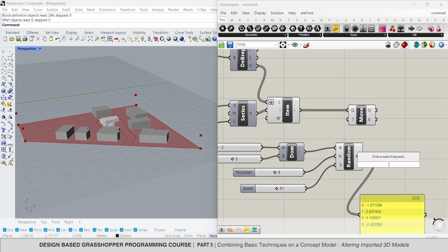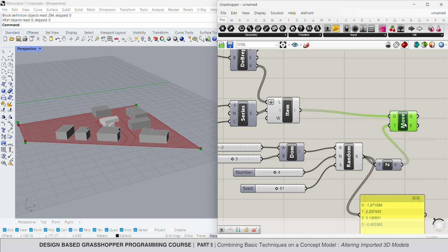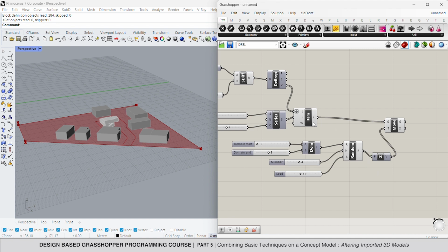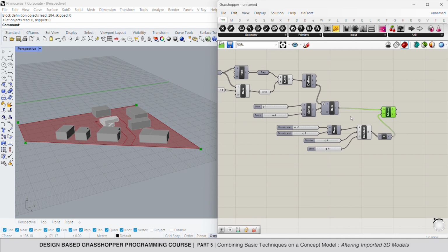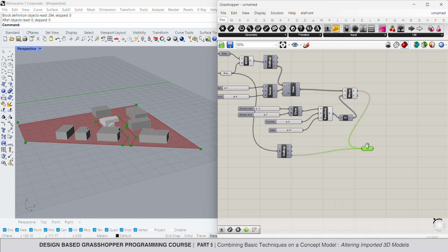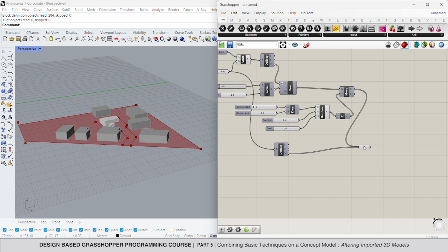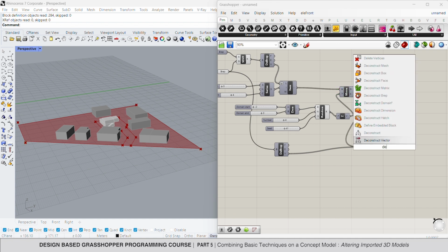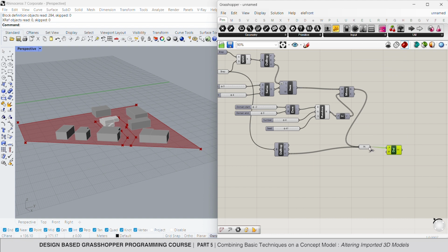Now we can take the Z unit vector to connect it to the move command. Then we need the vertices on the smaller surface we have. For that, we can use the wrap command again. Let's now use the point parameter to keep these different points in there. Now we will use the delaunay mesh command to create a surface based on these points.